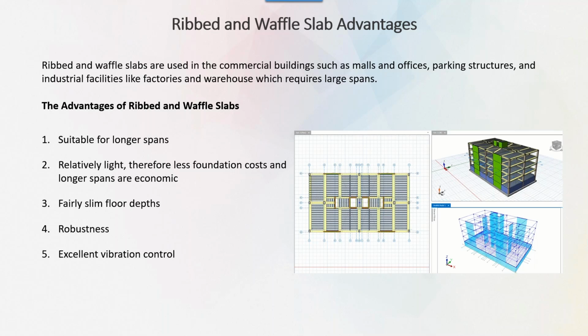They have fairly slim floor depths, so if you use, for example, a flat slab or other slab types, you can obtain slimmer floor depths. Of course, this is valid for the same slab span. We can also say robustness is an advantage of the waffle slab, and also excellent vibration control.